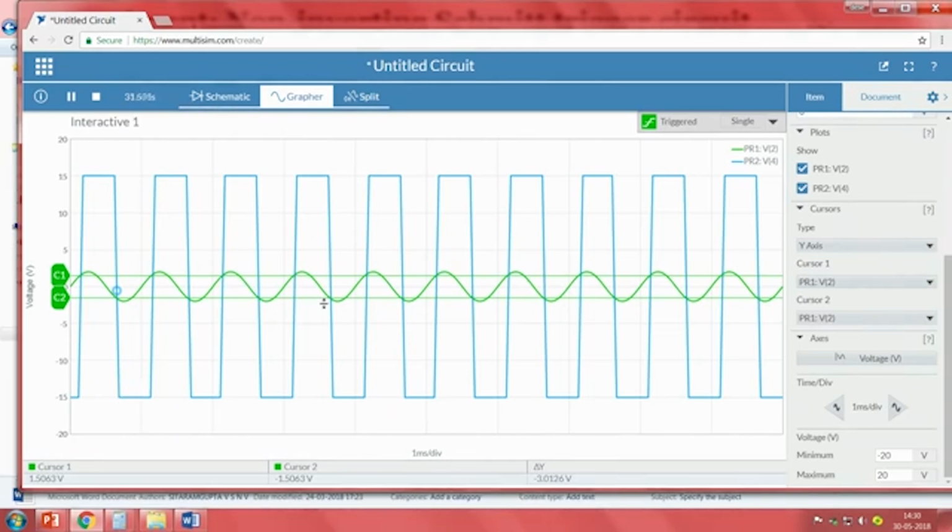But what is the difference that you observe from inverting and non-inverting type? In case of inverting, this would have been in a reverse way, meaning when the input is greater than C1, I would have gotten minus VCC, but when the input is lower than C2, the output would have been plus VCC. But in this case, the output is similar to the input, similar to the threshold. When the input is greater than the higher threshold, it goes to plus VCC, right.